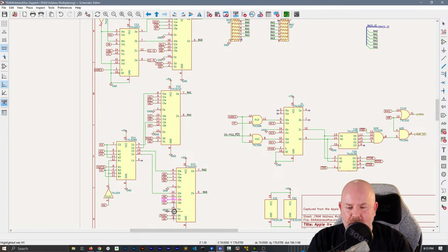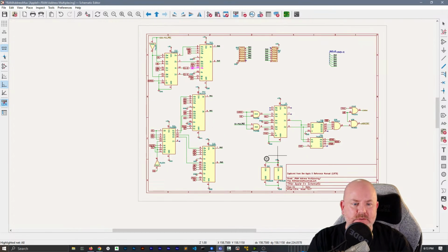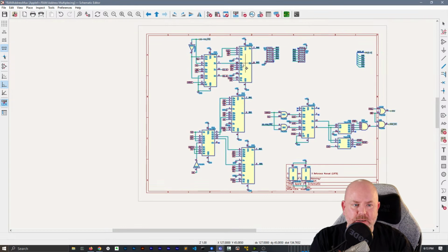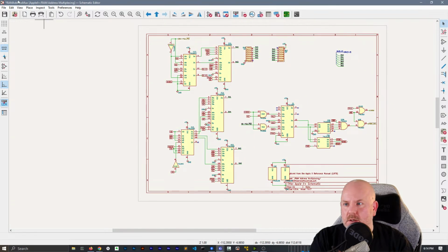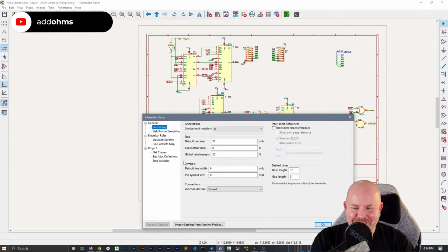Is that what's going on? Because I see an A8. 1250. Yeah, that's what's going on. These are address lines. Okay, which makes sense because this is for RAM multiplexing. This is, I think, responsible for switching between CPU and video phases. Well, no, actually what it did is it overwrote the mapping of Z to Q for both of them, which makes no sense.